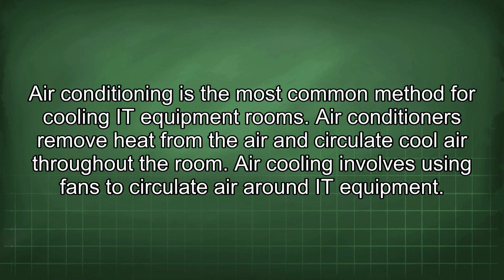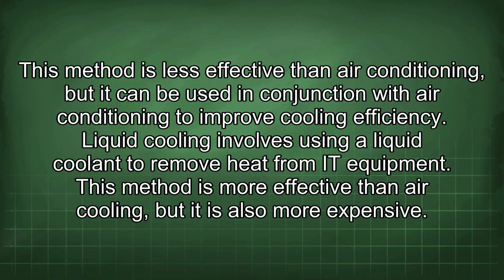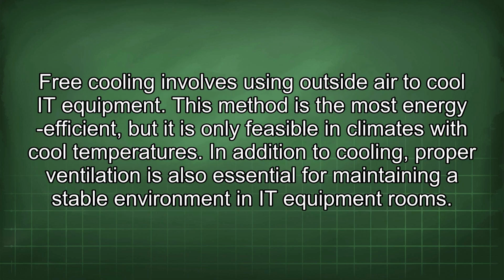Air cooling involves using fans to circulate air around IT equipment. This method is less effective than air conditioning, but it can be used in conjunction with air conditioning to improve cooling efficiency. Liquid cooling involves using a liquid coolant to remove heat from IT equipment. This method is more effective than air cooling, but it is also more expensive. Free cooling involves using outside air to cool IT equipment. This method is the most energy efficient, but it is only feasible in climates with cool temperatures.